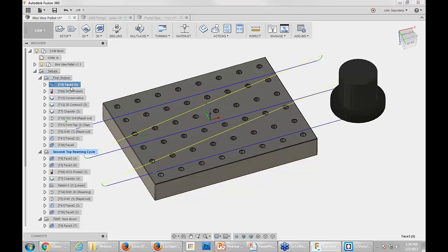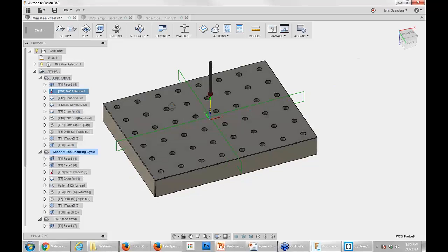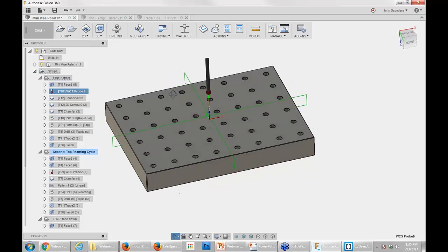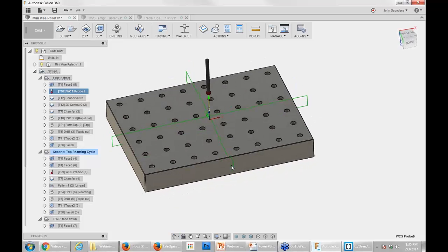So cool to me. After I deck it off, I then go ahead and probe it. My probe is tool 99, and that updates the G54 or 55 for that part. I probably don't need to be redoing the Y because it's in a fixed jaw orange vise, so it doesn't move, but the X will move each time I put a part in, which is nice because I don't have to use vise stops anymore.